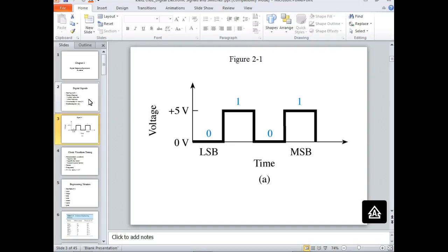So Alabama Power generates 60 Hertz. So their frequency is 60 cycles per second. But they generate a sine wave. They don't generate a pulse waveform, even though we can use it for timing. If you've got any clocks that lose their time when power goes out, then odds are they're timing off Alabama Power, because that 60 cycles is almost perfect, because of all the different devices that depend on it being 60 cycles. The voltage can change, but the frequency doesn't. Which is pretty neat.